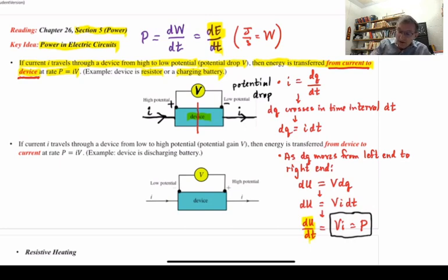Now the units, of course, just think about that a minute. The unit of current, you should know now, is the ampere. And the unit of potential difference is the volt. Let's think about those units a little bit. Volt is joule per coulomb. We need to remember that. Ampere is coulomb per second. We need to remember that. Multiply those units. The coulombs cancel. You have joule per second, which is watt, which is correct. So far, so good?